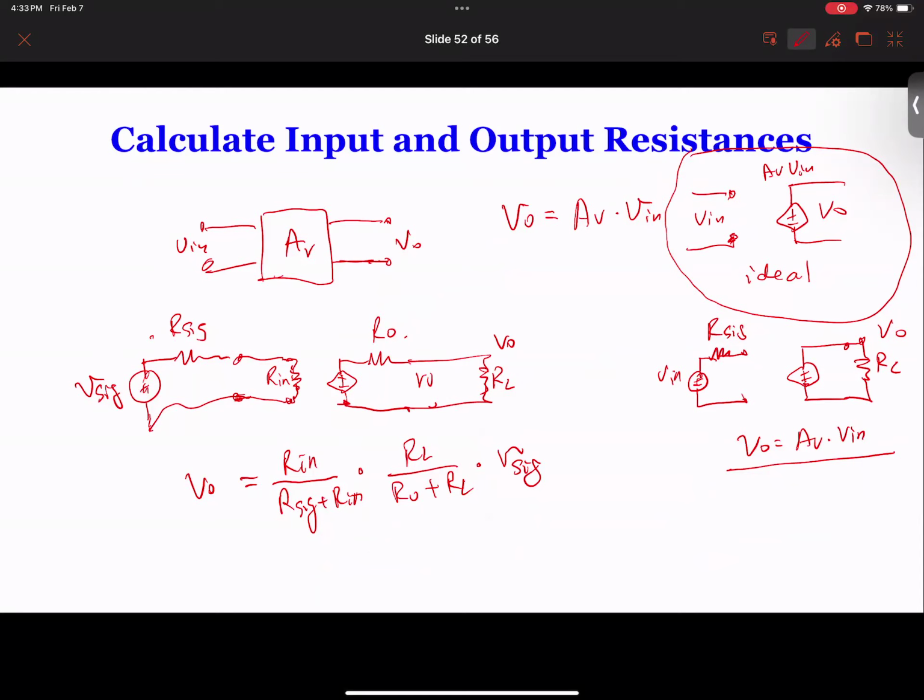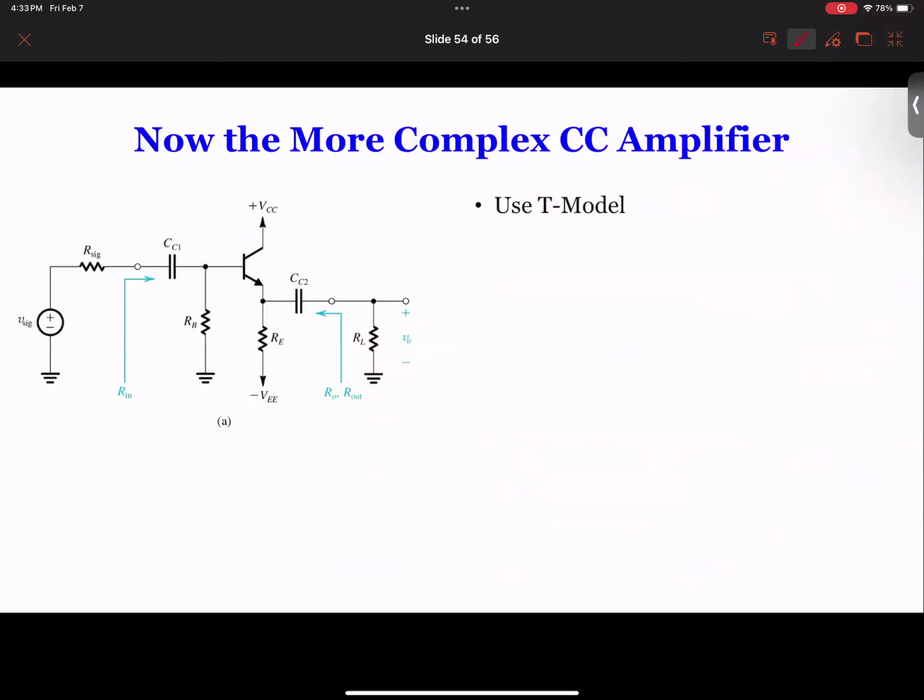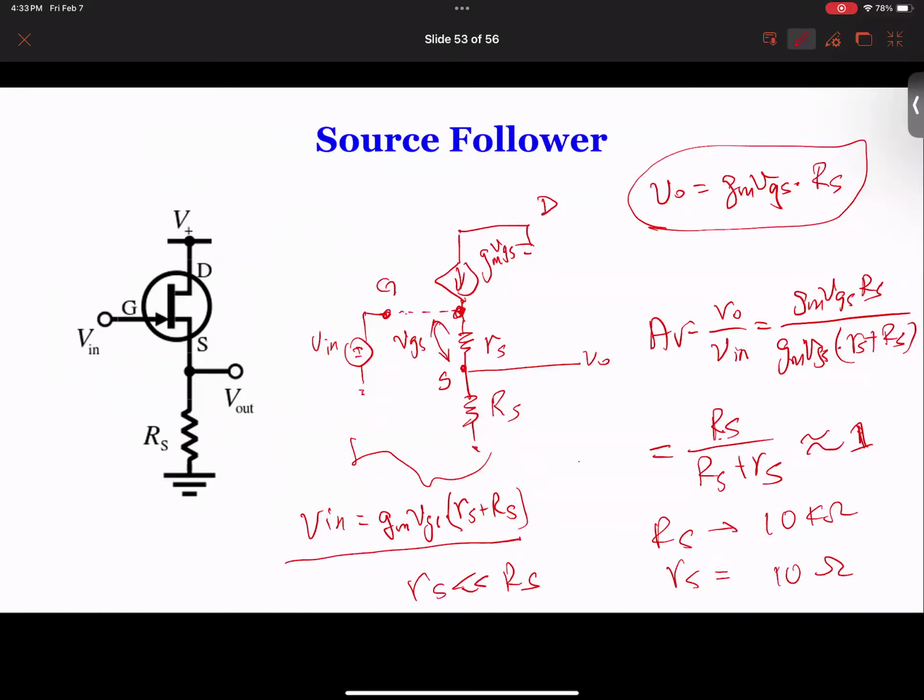And why is that? Well, I think we're going to skip that one, but we're going to stay here for a little bit. If you look at the equivalent circuit, because there's nothing connected here, the input resistance is actually infinity for the MOSFET. With the BJT, it is connected, but still the input resistance is very big. It's also almost infinity.